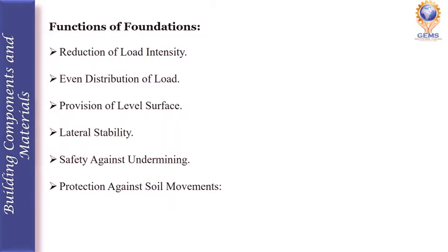The first one is the reduction of load intensity. So this foundation can distribute the load of the superstructure to a larger area. So what will happen? The total intensity of the load doesn't exceed the safe bearing capacity of the soil.